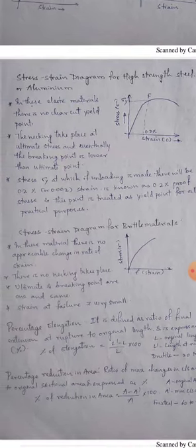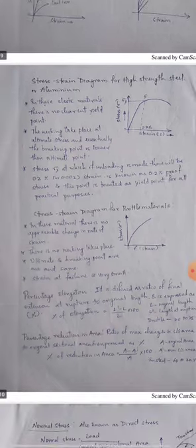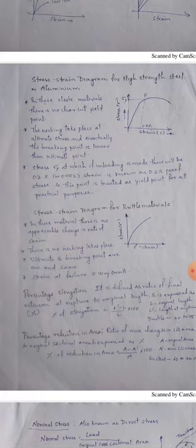Therefore, necking takes place at the ultimate stress, and the stress at the breaking point is lower than ultimate. Therefore this stress sigma y, on unloading, leaves a 0.2% strain. Therefore it is the 0.2% proof stress. This point is treated as the yield point for practical purposes. Therefore, for an HYSD stress strain curve, the yield point is the 0.2% proof stress.